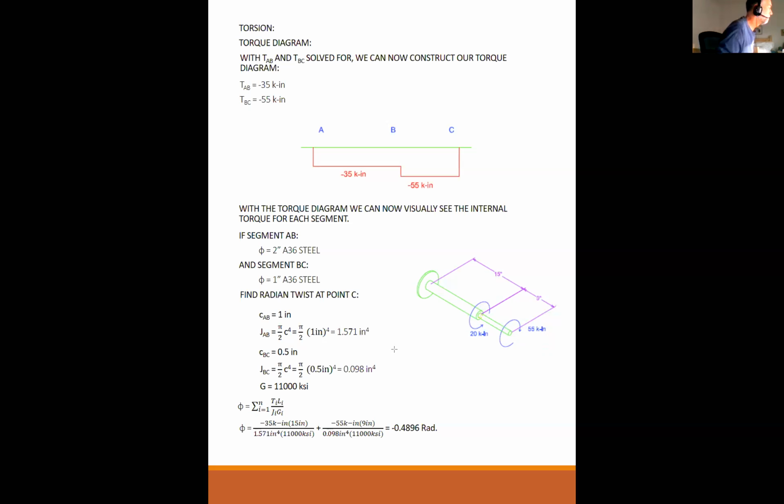When you get into more advanced topics, it does get a little more complicated, like reinforced concrete beams. When you apply a torsion to a reinforced concrete beam, the concrete tends to try to crack and push itself apart, and the rebar in there resists that load. So there actually is a normal force due to an applied torsion, but forget I ever said that. Doesn't apply to this.